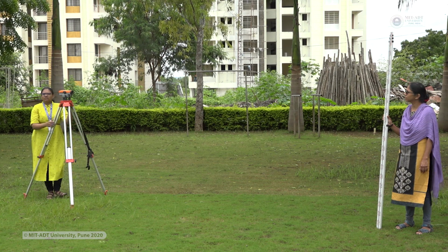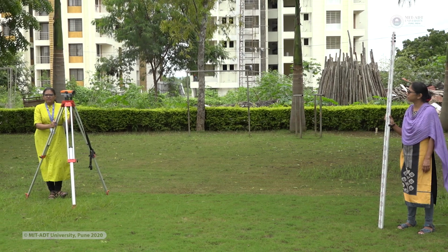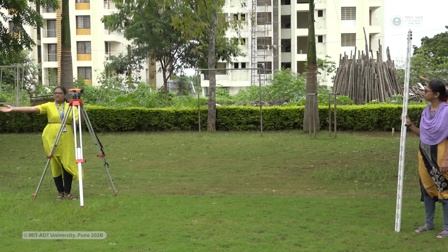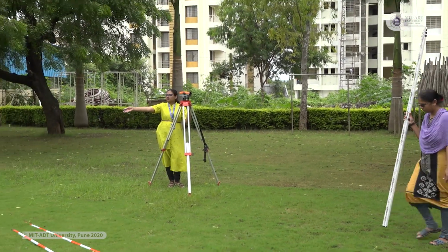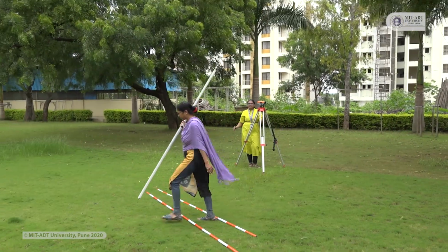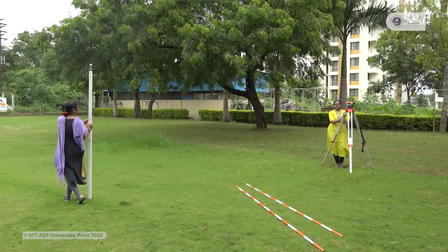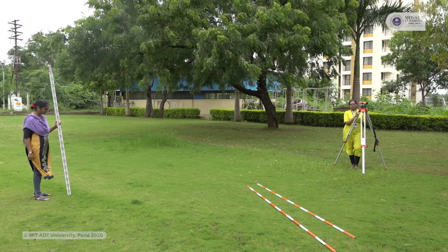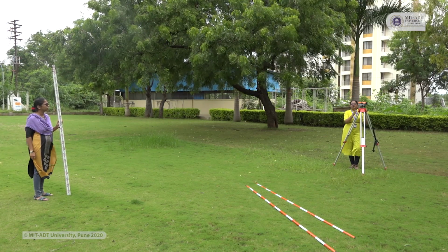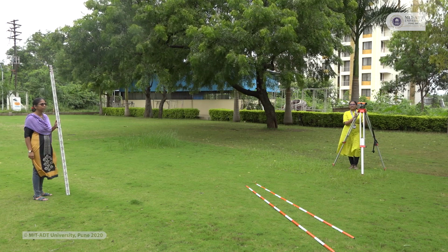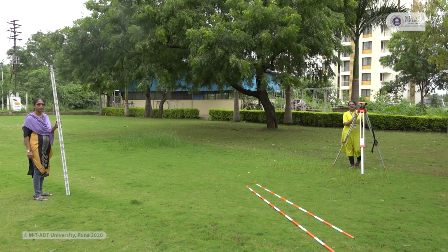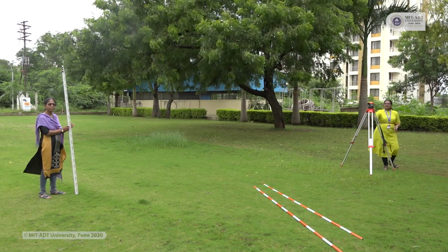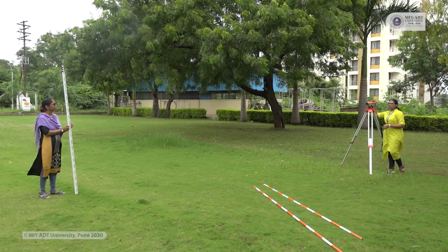Now we will take the fourth reading, but before that, we have to make sure that we shift the instrument after taking the fourth reading. So we will shift our staff, shift our observation point to the next point, and after taking this reading we are going to shift our instrument also. So that will be our change point. Before that you have to write down this reading in the column of the fore side, because at this point we are shifting the instrument and we are measuring the side of our object. So this is our change point. Now I will bisect the object again by using the prism which is provided on the top of this telescope.